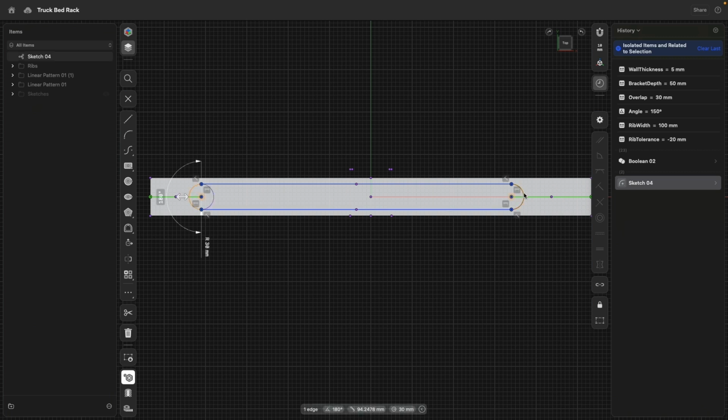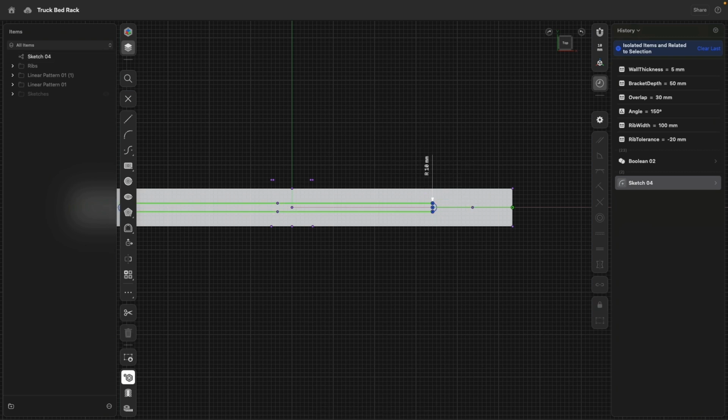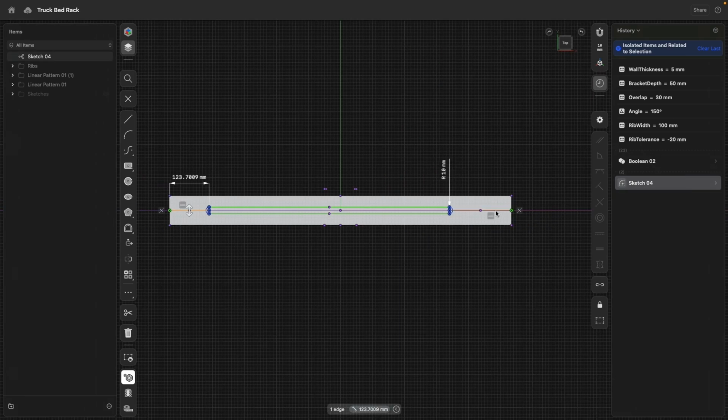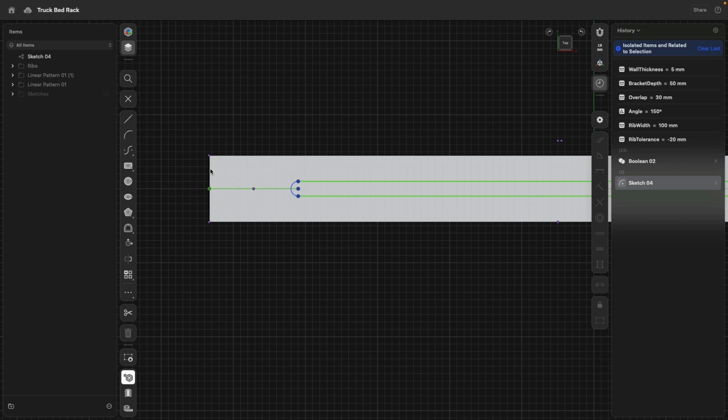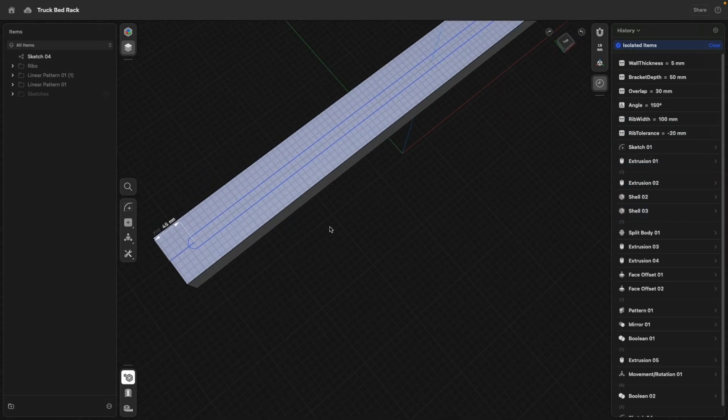Very good. These circles, technically speaking, can also be equal. The radius 10 millimeters. I make this a little bit bigger so it's easier to see. And this is kind of like the hole where the through would go through. Then these two first green lines, now I will select and make equal to. Beautiful. And now, how long is this line? So that is 90. So if we think about this one, that should be 90 divided by 2. There we are. From here to there and there, that's always the exact distance. Perfect. This will be very useful soon.